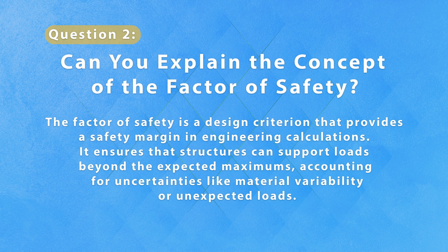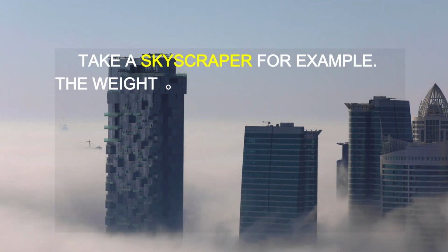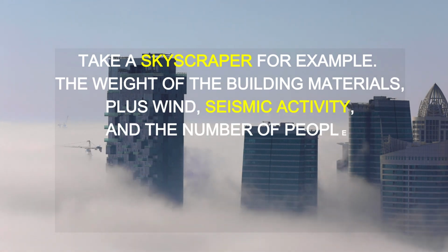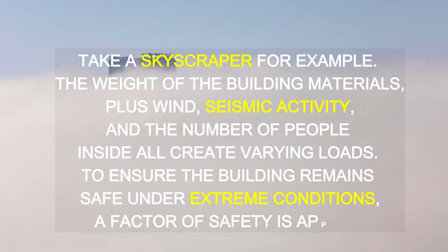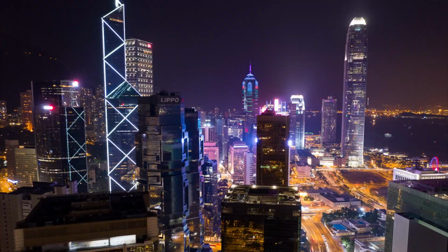The factor of safety is a design criterion that provides a safety margin in engineering calculations. It ensures that structures can support loads beyond the expected maximums, accounting for uncertainties like material variability or unexpected loads. Take a skyscraper for example. The weight of the building materials, plus wind, seismic activity, and the number of people inside all create varying loads. To ensure the building remains safe under extreme conditions, a factor of safety is applied. So even if the actual load exceeds the anticipated load, the structure won't fail.